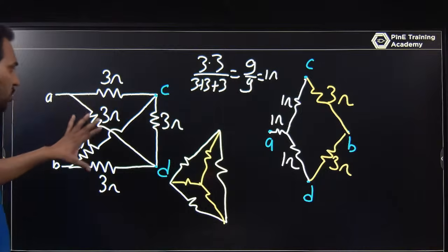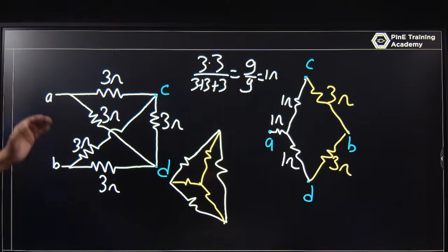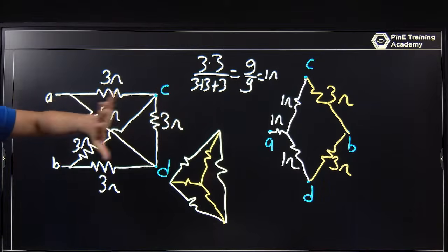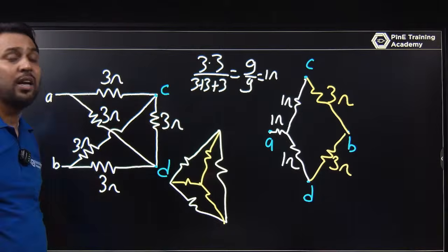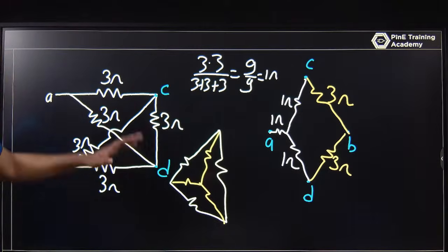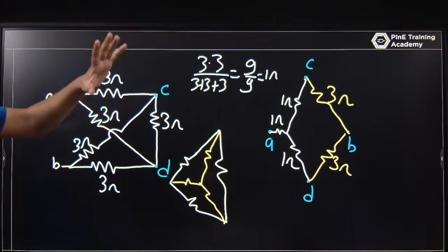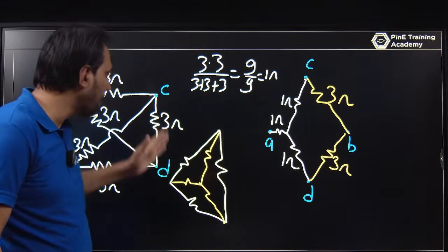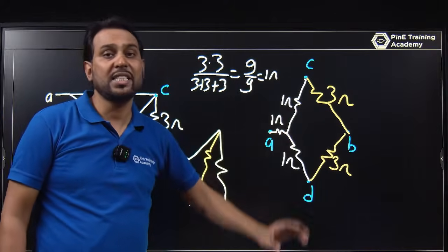I am saying that you have one question where I have AB. You are trying to determine what is RAB. So I just use nodes here, that is C and D. Of course, there is no common, so that's why every node is different. So this is A, B, C, D. Whenever you have 4 nodes, always try with a Wheatstone bridge. So I designed it with the help of a Wheatstone bridge that you have 4 nodes A, B, C, D, and we find, okay, this is a problem. In between CD you have an impedance.